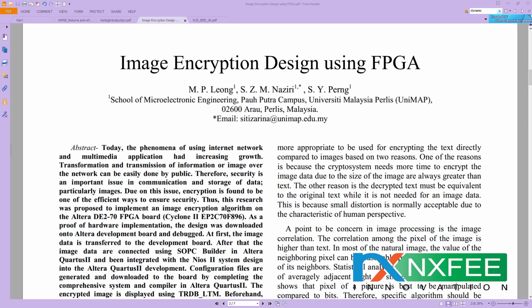In this work, the different PRNG approaches are analyzed based on randomness quality using the NIST test suite, along with hardware resource utilization and encryption security. The chaos-based PRNG is then integrated into the stream cipher encryption system, where the image pixels are transformed using bitwise XOR and chaotic substitution operations. The encrypted image is decrypted using inverse transformations and displayed on a TFT display, ensuring real-time validation.